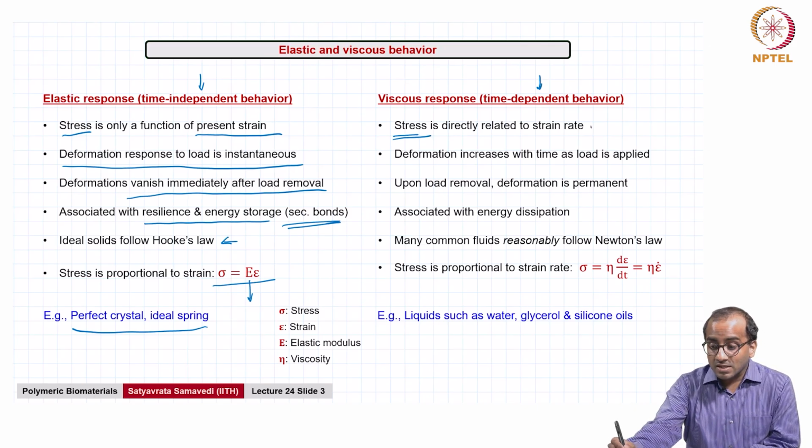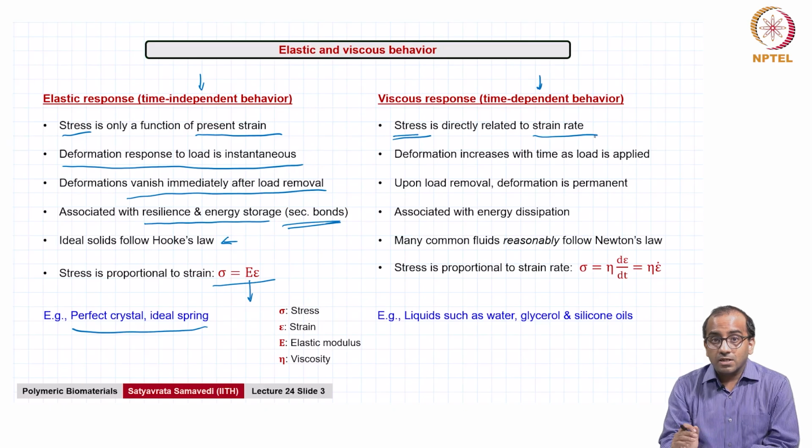So, stress in this case is directly related to strain rate rather than the strain itself. Unlike purely elastic solids where stress is proportional to the strain, or load and deformation are related, here once you apply a stress, because you can't lock in deformations in any physically meaningful sense, what matters more is the rate of deformation, and here stress is directly related to the strain rate.